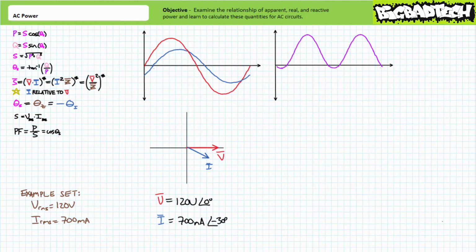Voltage and current are in almost every aspect exactly the same as in our previous example problem, only this time, current lags voltage by 30 degrees. Our earlier thought experiments led us to believe that given an increased phase shift between current and voltage, we should anticipate an increased cyclical exchange of negative and positive power, and as such, reactive power should increase. Given a larger portion of apparent power is being directed towards a reactive interchange, we should expect a smaller portion of it to be directed towards real power. Long story short, real power goes down and reactive power goes up.